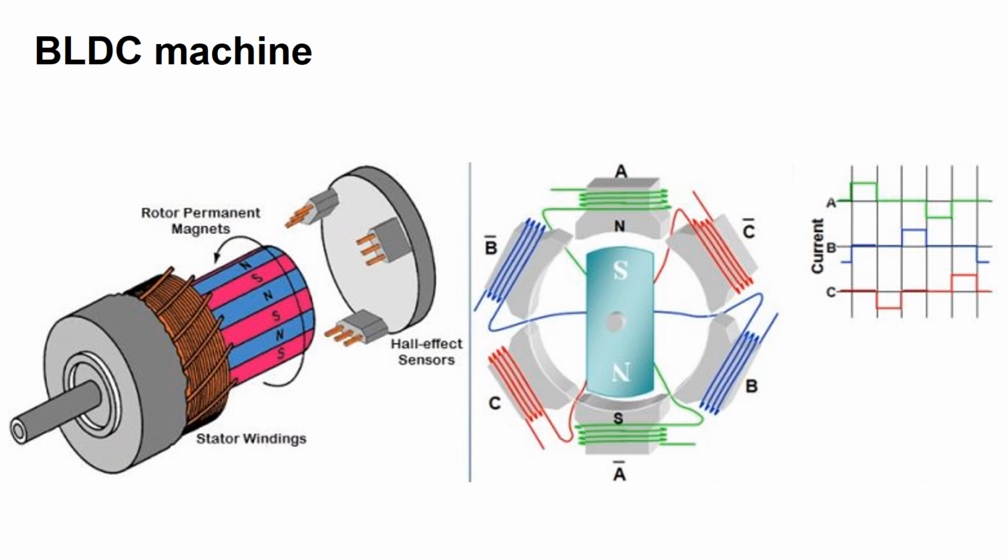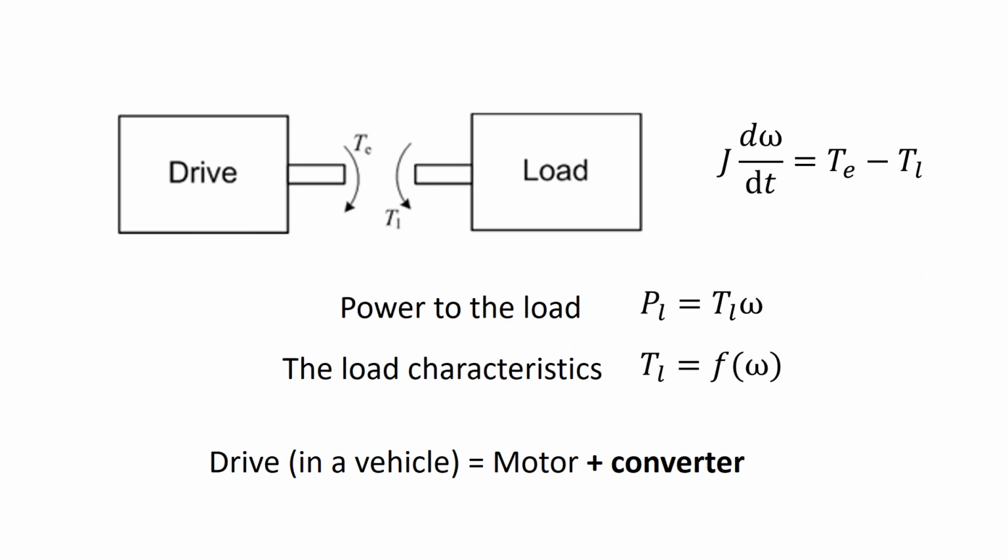In this slide, we can see the anatomy of a brushless DC machine. On the left, we can see that the stator and the rotor functions are reversed. The stator contains windings which carry current, and the inner rotor is constructed with strong permanent magnets to generate the required magnetic field. By synchronously energizing the poles A, B, and C, shown on the right, we can produce torque which acts on the armature. Machines like this can be constructed with many poles for smooth and continuous torque.